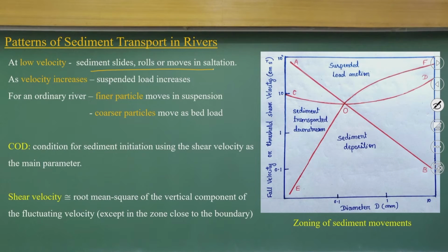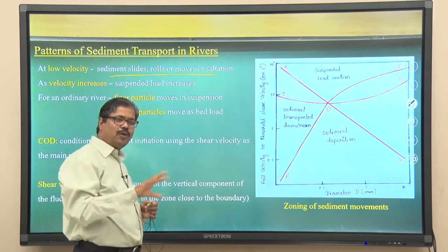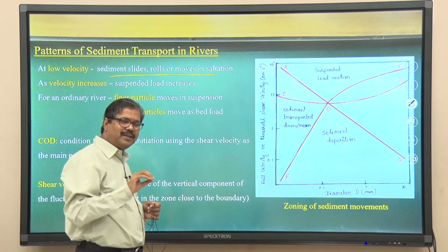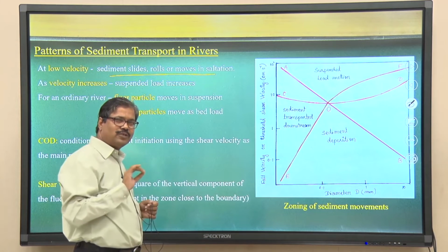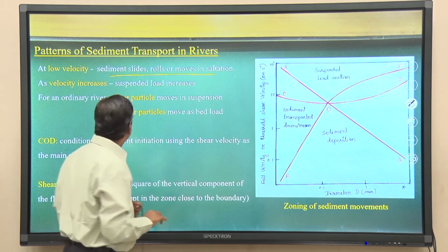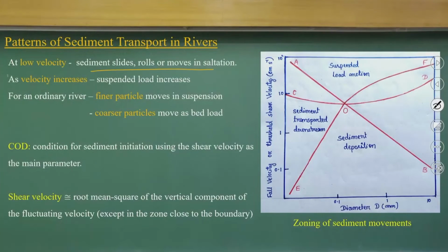In that case, you can observe in the plume or the river that the sediments are just starting bed load motions, just rolling and sliding. If you further increase the velocity or the stream power, what will happen? Suspended load will increase, and that is the final stage.